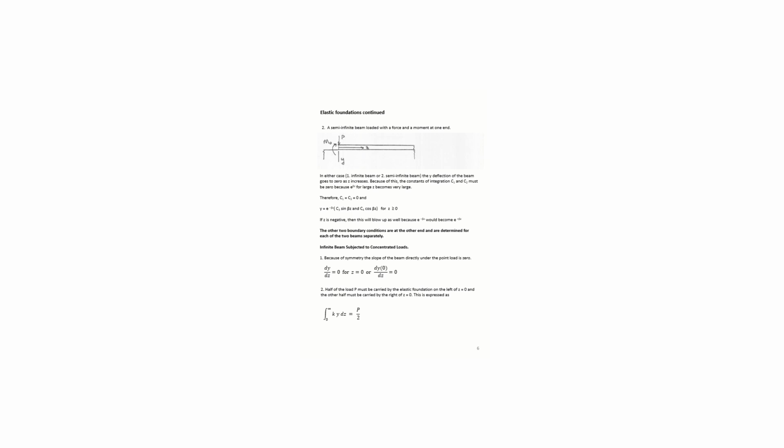So based on the infinite beam configuration that we're going to use, which essentially forces our beam displacement to go to 0 at one end, we can eliminate the coefficients C1 and C2, and our expression for our displacement can be given here as this equation, as shown, where we have e to the minus beta z.